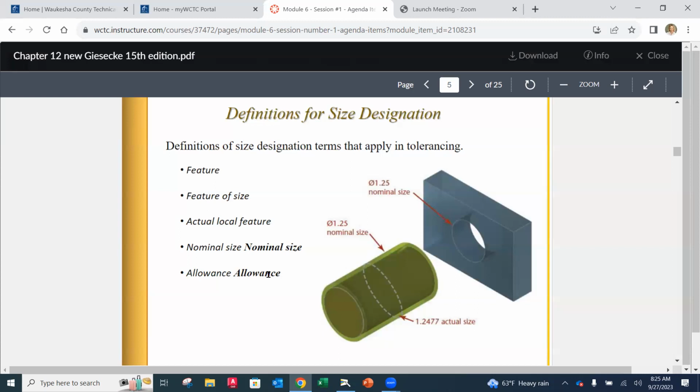So when we put bearings in place, we press them in so that the outer race is not going to move around. We don't weld them in. We don't screw them in. We press them in. And it's actually a pretty accurate fit, probably 4 or 5 decimal places. And then there are other types of elements that we would press that might even require hammering it, or convincing it to get into place, or pressing it in.